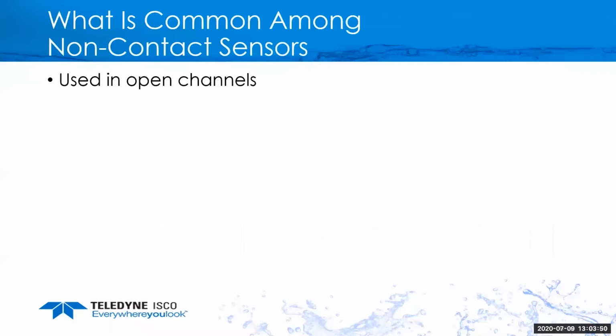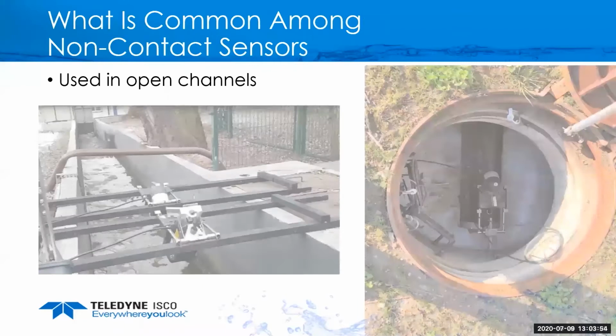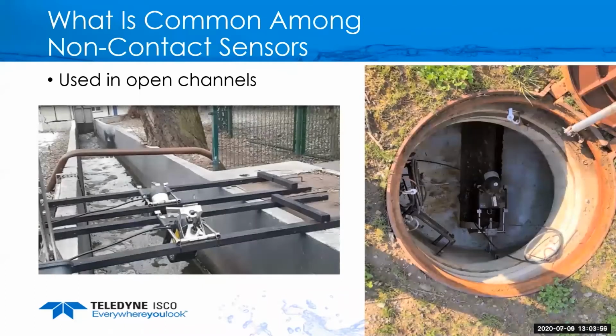So let's start. What is common among non-contact sensors? They're both used in open channels. And as you see here on the right, we can use them in round channels, or we can use them in rectangular channels. The size of the pipe can vary from anywhere from 6-inch up to 20-foot wide channels, just as long as it is an open channel.